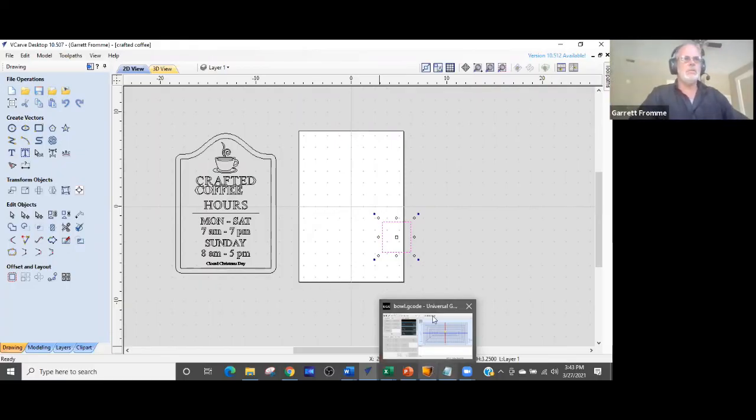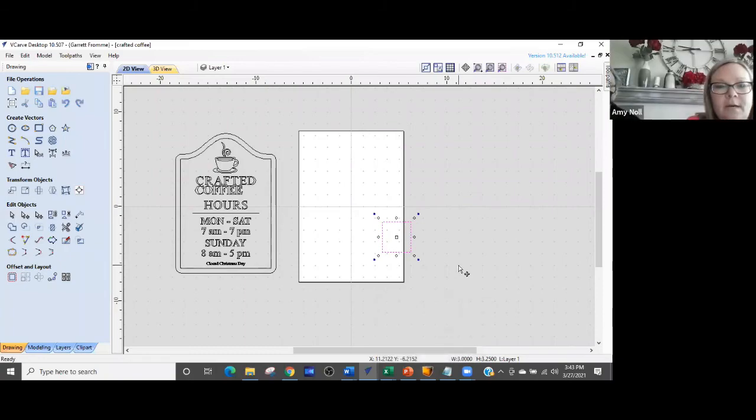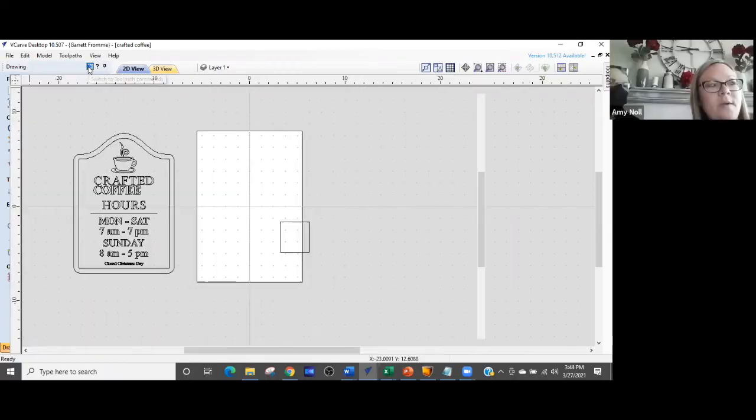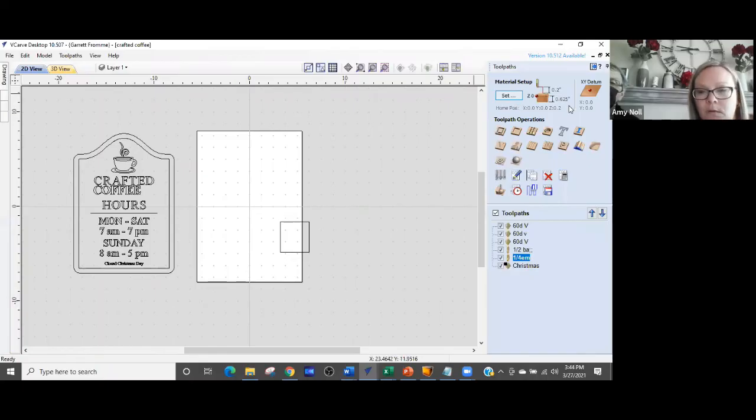Okay. Do we have other questions? I do have one, Garrett. Yeah. Hi. I just started actually doing the V-carve toolpath, and I don't know if I've just been getting lucky or what, but you don't have to set any start depth or max depth, right? Because I've just been running it and getting what I'm getting. How do I know it's not going to go through my material? You need to set a start depth. Mine's always at 0. Okay, that's your start depth.